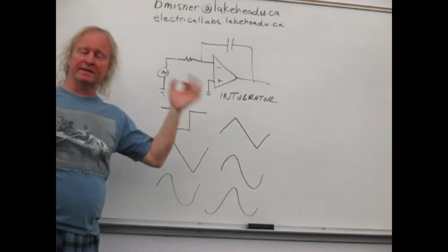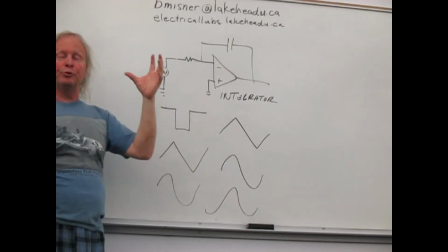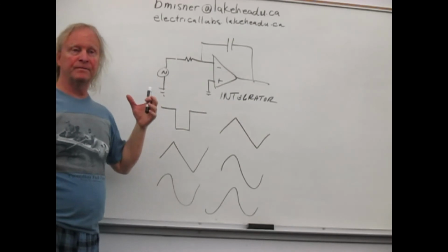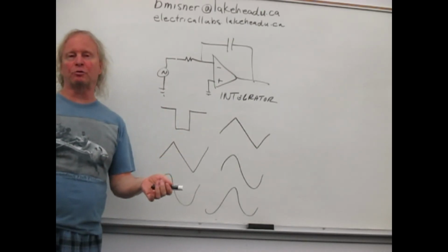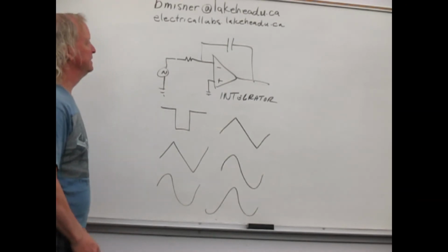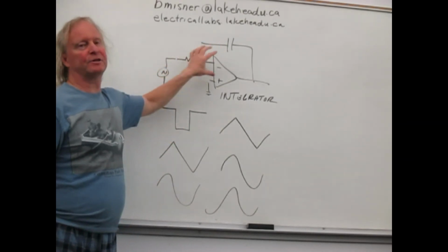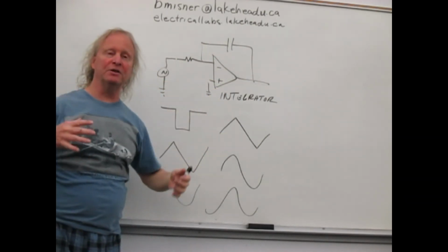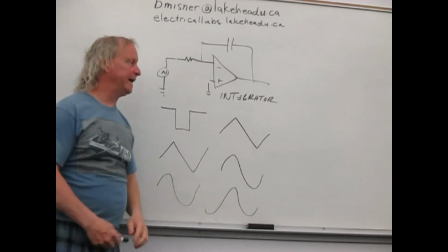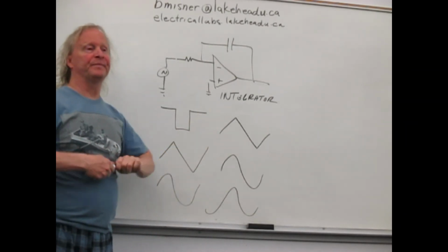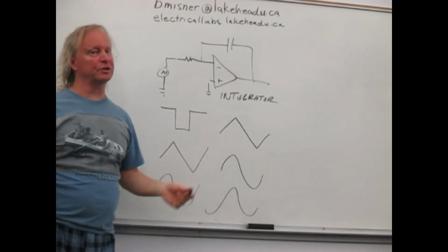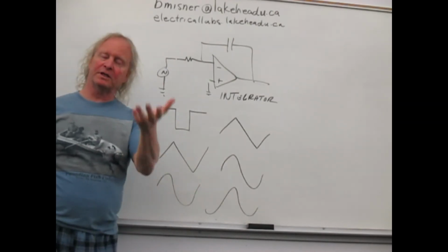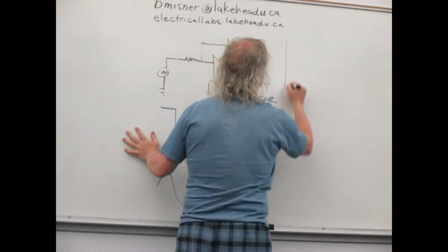The derivative is the differentiator, and this is the integrator. So you put these things together and you can use them as the process control circuitry. And then when you're tuning your controller, and you're going to have fun doing that, you're going to be changing the parameters of the integrator, differentiator, and the proportional to make your system function in a certain way. Okay? And so one of the number one ways of tuning your controller, which isn't always the best way, again, it depends on your application, they call it quarter amplitude decay, right?